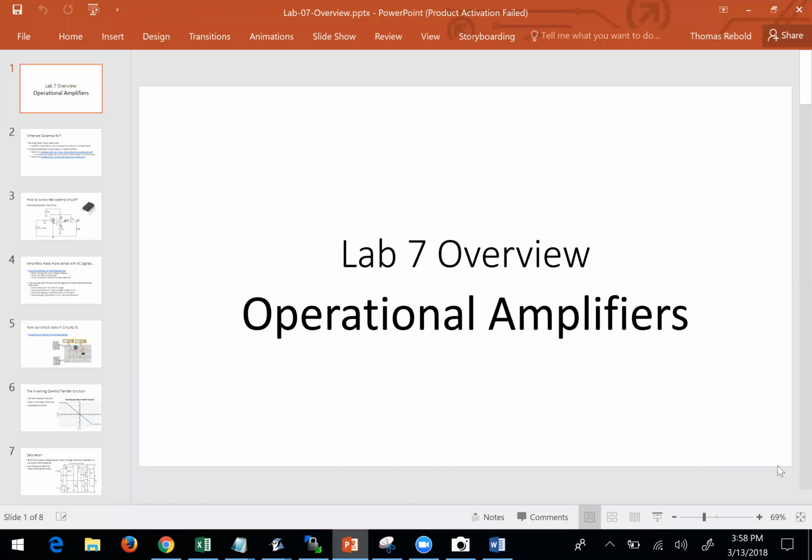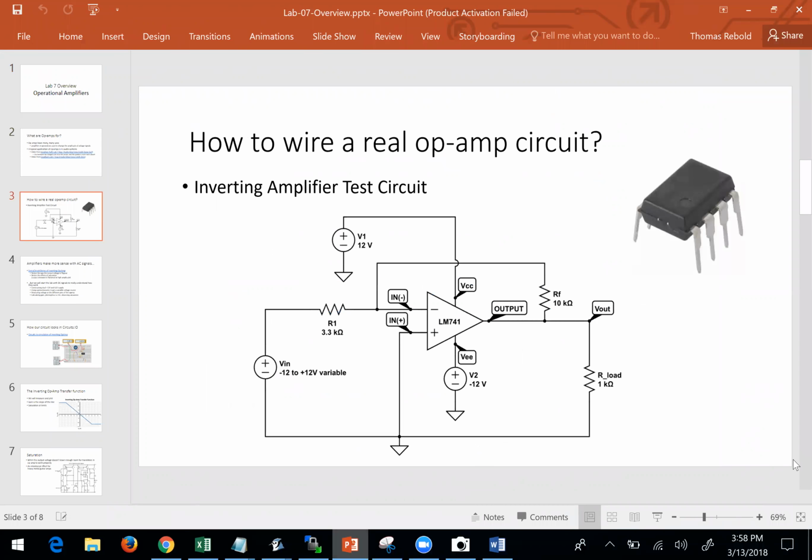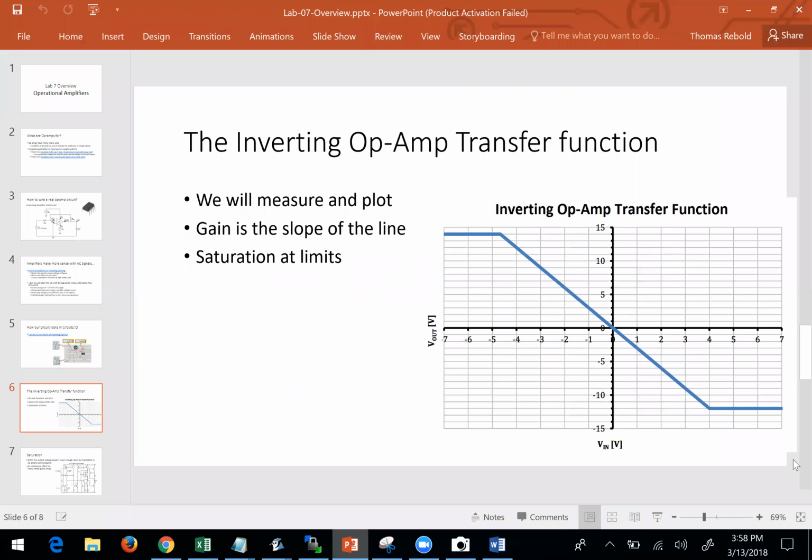So when you're in the linear range of the op amp, the output is going to be A times (VP minus VN). Remember the model of the op amp? Inside that op amp, there's a dependent voltage source that equals A times (VP minus VN), right? And when you're in the linear range, that's true.